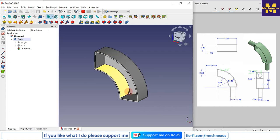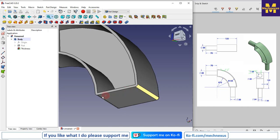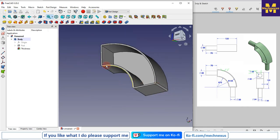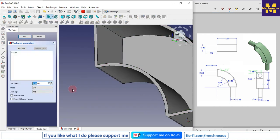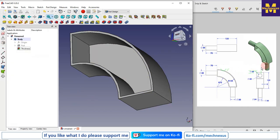Now we will make this pipe. So for the pipe, we can see here a radius at the corner. We will go to the edit thickness. So joint type is an arc. We will give the intersection because we do not want the corners here. I will say OK.